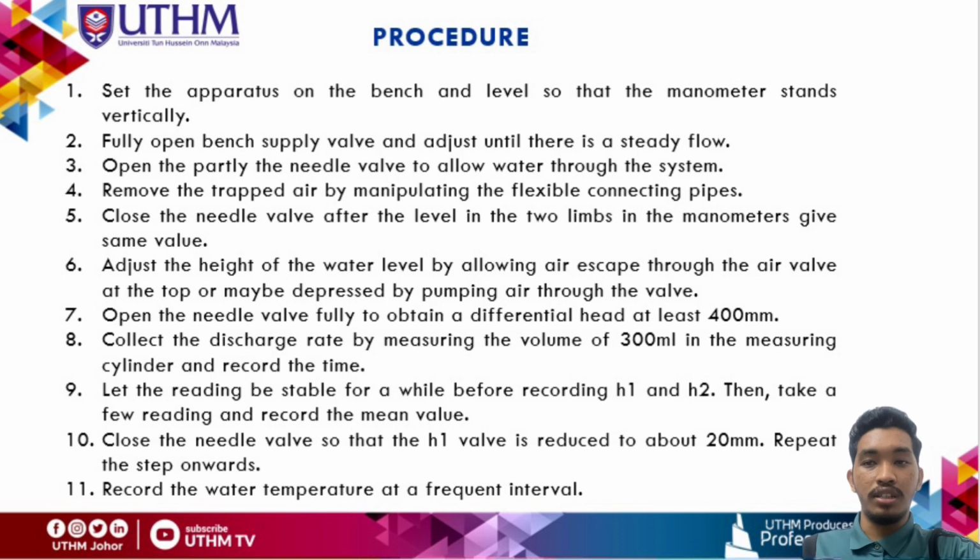Then take a few readings and record the mean value. Tenth, close the needle valve so that the H1 value is reduced by about 20 mm, and then repeat the steps onward. Lastly, record the water temperature at frequent intervals.